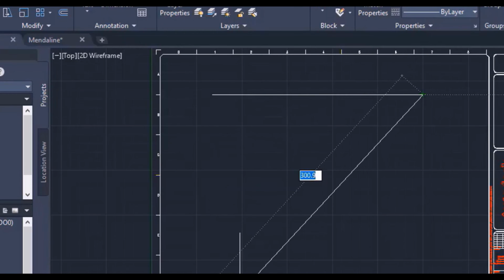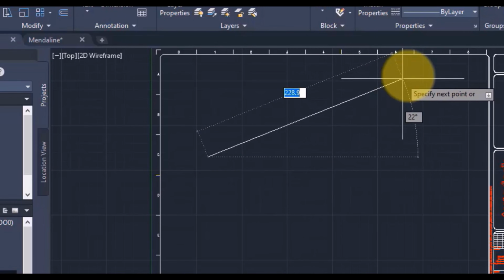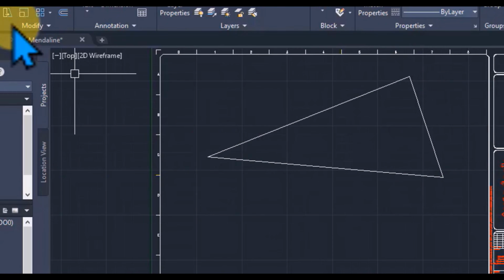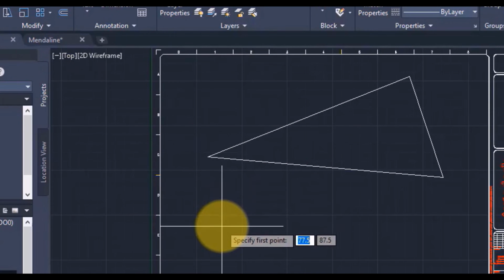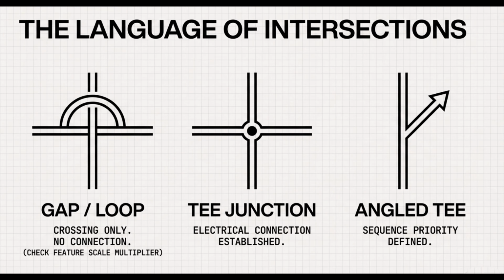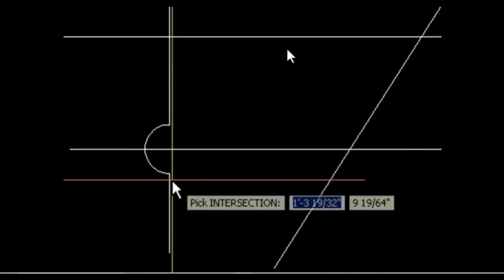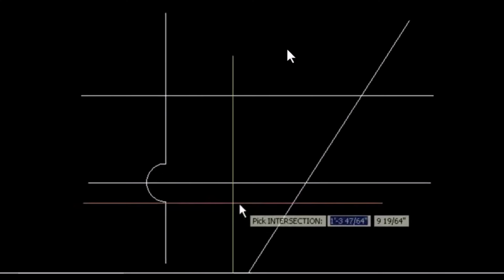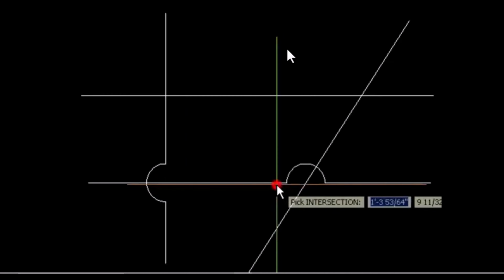There was a bit of drama in that CAD Tutor forum source we looked at about connections. A user was incredibly confused about the difference between an intersection and a gap. The classic crossing debate. This is where personal preference meets software rules. The issue is when you have two wires crossing paths, they don't touch electrically. So some people want a loop, that little hump to show it's jumping over. Some just want a gap. And the modern standard, like IEC and others, is increasingly just a solid line. It relies on the fact that if there's no dot at the intersection, they aren't connected.